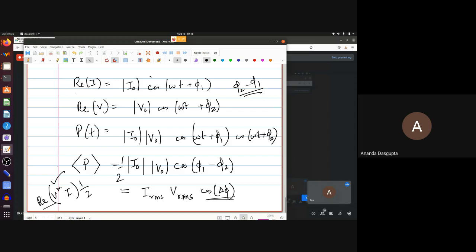Okay? The point is, complex currents and voltages are so useful that people don't really want to give them up. So even in non-linear situations, you will see people using currents and voltages which are given by complex exponentials. But then you have to bear in mind that before you do a calculation, you have to take the real part. And that's very different from taking the real part after you do the calculation.